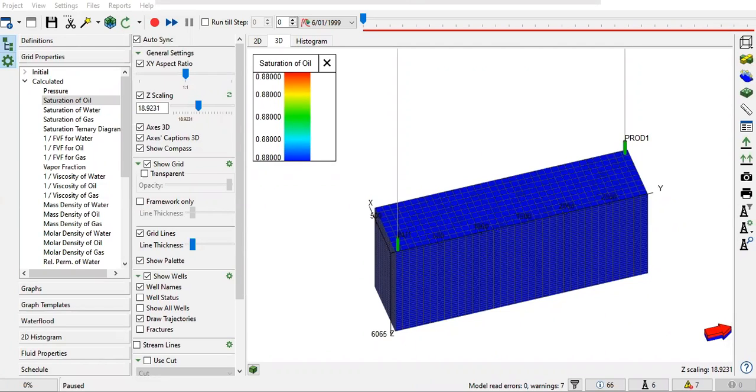So again, we will continue our learning on reservoir simulation using tNavigator software, and we will use sample cases from tNavigator. We can learn a lot from those cases, like the one we have right now. In this case, we will perform alternating water and gas injection to improve oil recovery, and we will use CO2 as the injected gas. Later on, we will expand the case with CO2 dissolution. So you can also connect it with the CCUS topic, carbon capture, utilization, and storage.